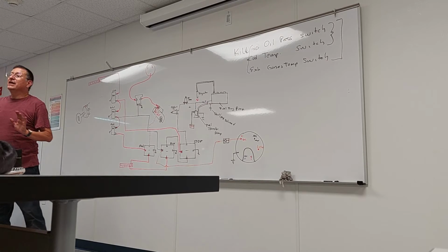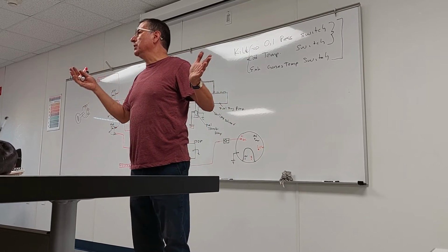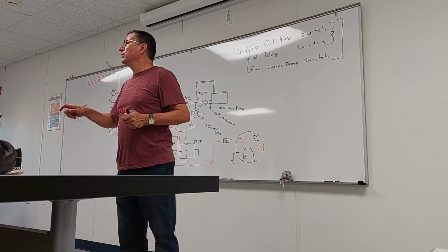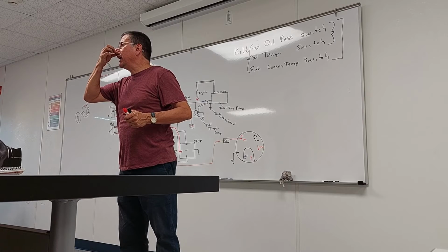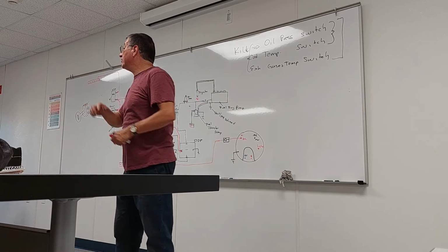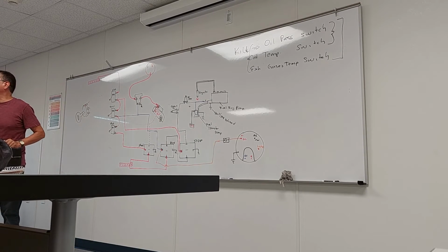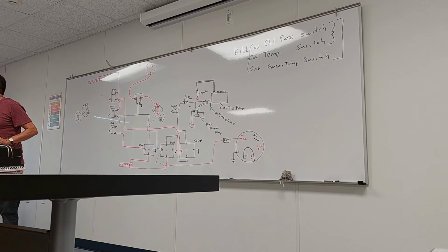Because there is no fuel. Right. You have two options to stop an engine: if you cut the fuel, or if you cut the air. If you cut the air, it stops immediately. For that reason, if you are inside of the boat working in the engine room and you see fire, you need to stop the engine quickly.